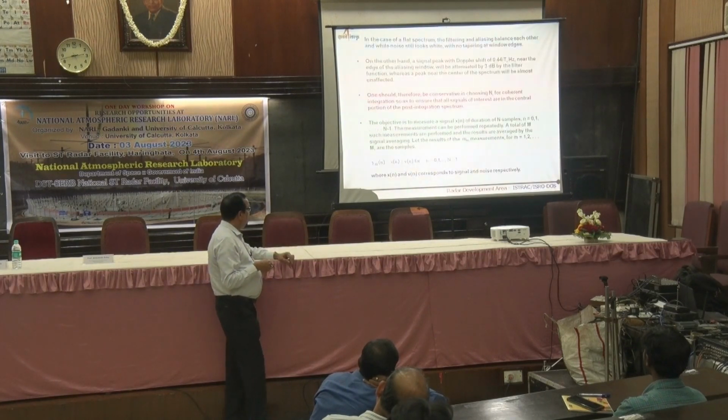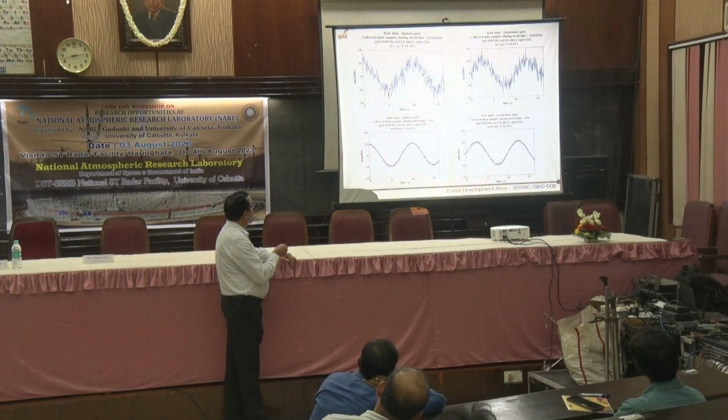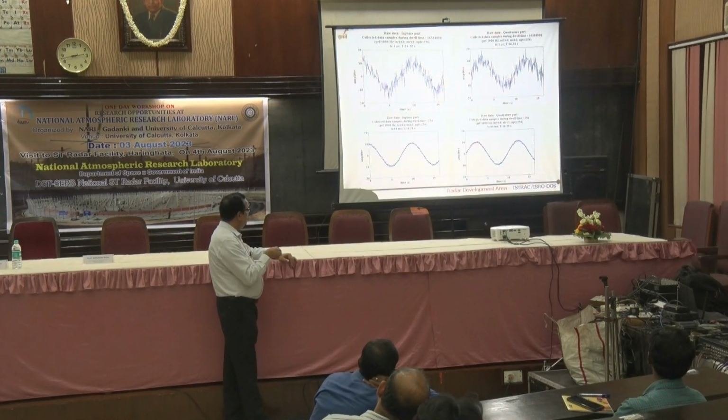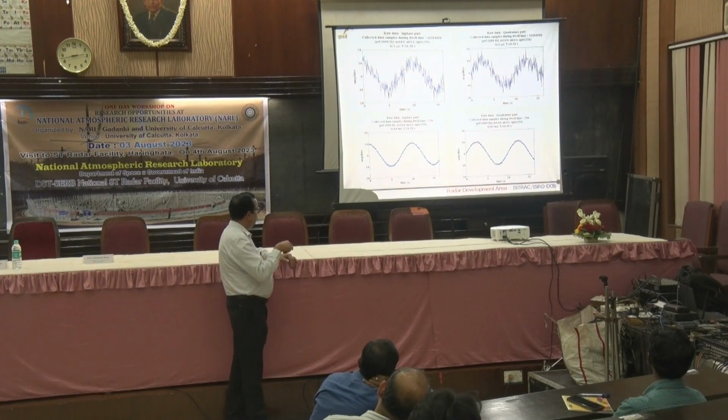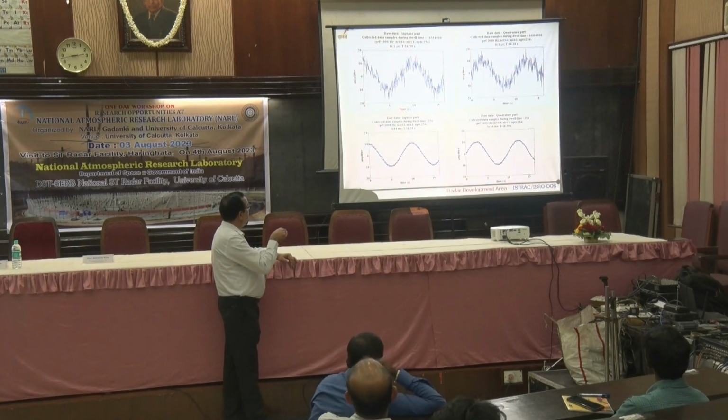Okay, what I already explained to you, let me skip here. So this is the signal. Essentially, when you look at your original signal without integration, and then I integrate, you can see that the noise fluctuations are getting reduced. The timestamp here is slightly different. It is actually 64 milliseconds is the total timestamp, and here it is only plotting 15 milliseconds.